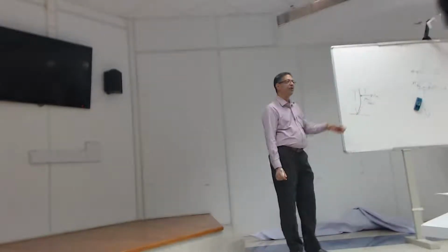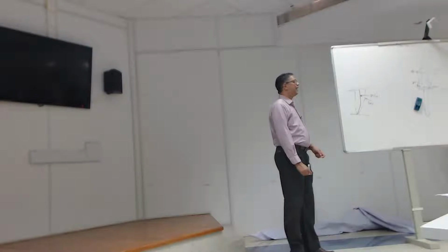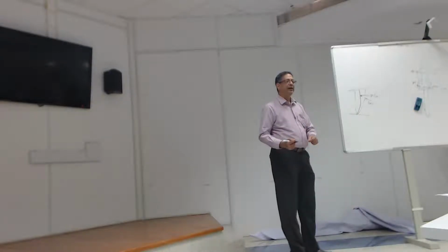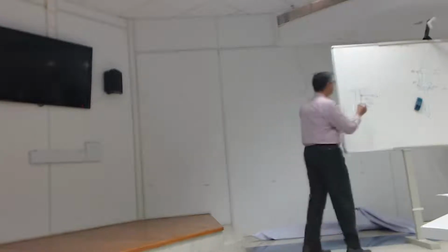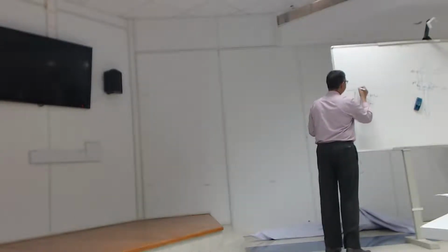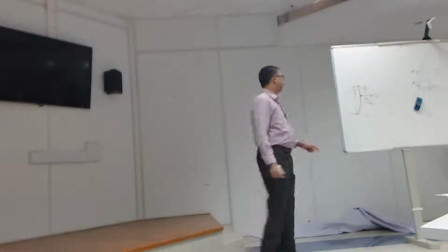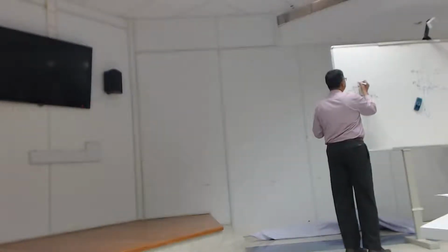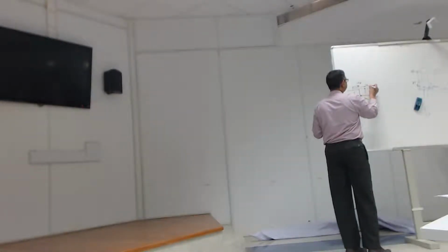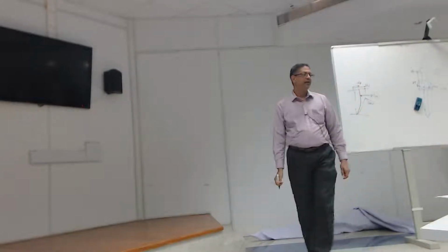You remember I've drawn this earlier. What we're saying here is clearly a good measure of telling how much the kinematic load is, to say what is the ratio of that displacement to that displacement. Make sense? So one is the pile displacement, which is UP, and that is U naught. Yeah?